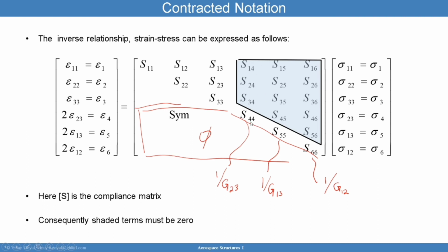You can also see here that this shear strain, when it's applied, because these 2 are 0, doesn't interact with the other 2 shear stresses in the other 2 planes. So far this is quite successful, and now we're left with figuring out how to measure and how to find this 3x3 matrix, because all this is known, and these 3 can be readily measured.